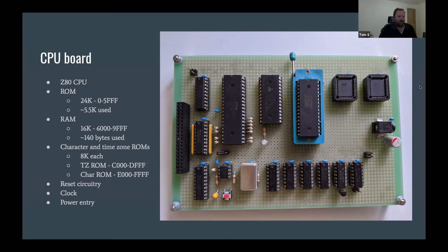I just thought, for ease of prototyping, that I can just pop out whichever ROM I need to change. But it's certainly possible to fit all of this into one ROM. You can see over on the left, I only ended up using about 5.5 kilobytes out of what is technically a 1 megabit ROM. So there's plenty of space to hold it, and still plenty of space in the memory map to be able to combine all of that into one single ROM.